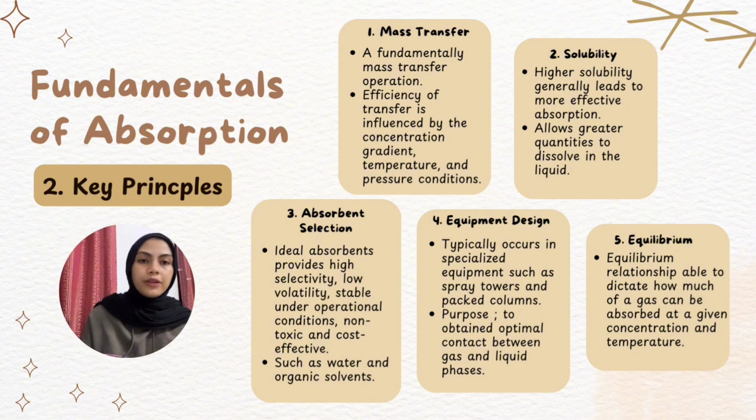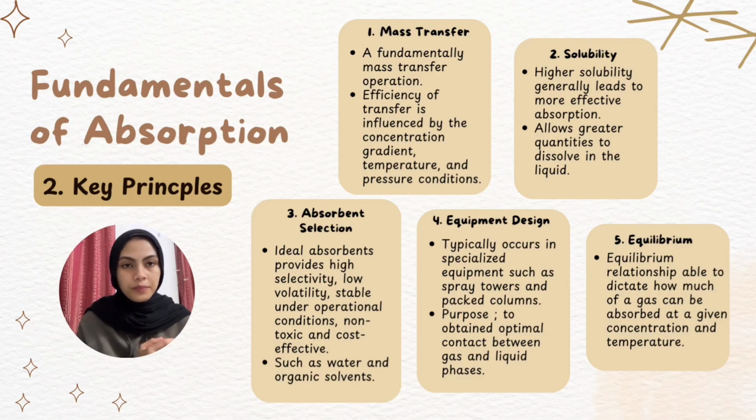And the fourth one, we have equipment design, where absorption usually occurs in specialized equipment such as packed columns and spray towers. The purpose of doing absorption in such specialized equipment is that we want to obtain optimal contact between the gas and liquid phase. And then the last one, we have equilibrium, where absorption provides an equilibrium relationship,